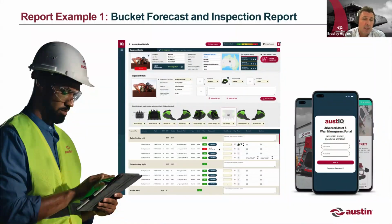Now, with the pods that are out there at the moment and are proving very well in trial, those pods will have a sensor in them that is doing a live thickness testing recording, which is going to take the need away for someone to physically have to go out to the site, hop in the back of a truck body and measure it with manual thickness testing. So at any time, you'll be able to log into the platform if your asset is fitted with pods, and you'll be able to do a download and see the performance of that tray and what thickness is remaining on the life of that asset.